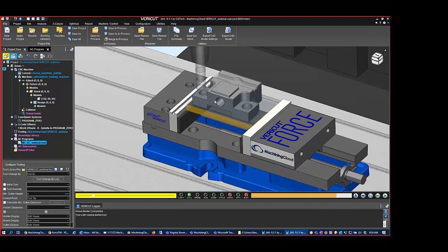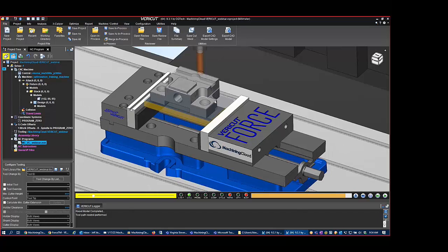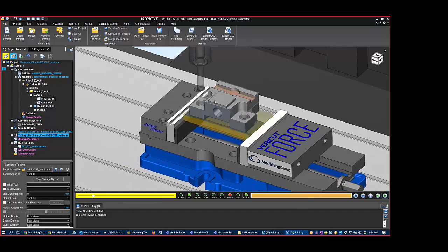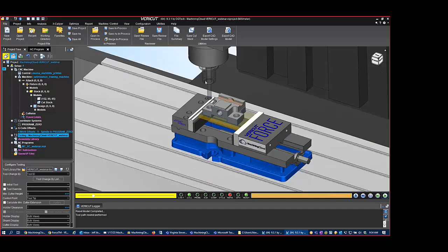And you can see here, this will be done in just a moment, drilling those couple of holes, milling that slot. And we've been able to use that data that Charles built as far as the tooling goes and use that in our simulation here. So that's fantastic from the first aspect, that we can make sure we've got accurate tool geometry in here for the cutter size, as well as clearance if you get into some very tight areas on fixtures and whatnot, or whatever the design of the part may be.